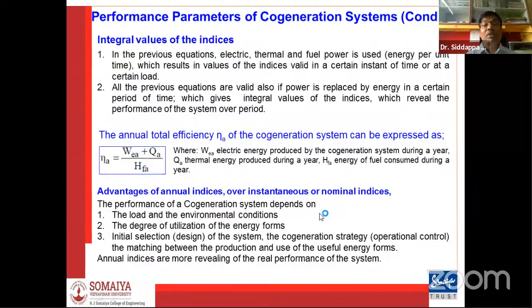For example, because of too much cold environmental conditions, to generate a certain power output from a system, I may send more fuel to the combustion chamber, because the air is at a lower temperature. To get the same required temperature of the air when I burn in the combustion chamber, I have to send more fuel. Then automatically the BSFC or SFC of the plant will go up.